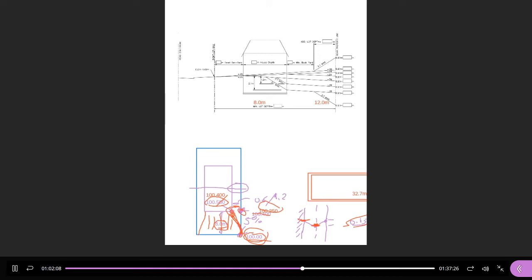But again, it depends on where the existing ground is. So if the existing ground, let me walk you through this again. If the existing ground is way up here, you're going to need to go minimum usable backyard, 3-to-1 slope, and then a wall. If the elevation at the back is in here somewhere, right? Let's say it's exactly here, then you have a full 3% lot.